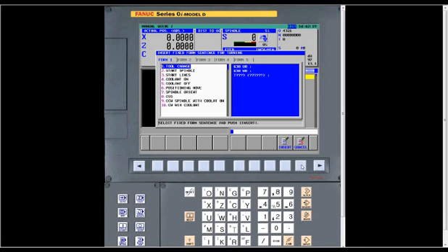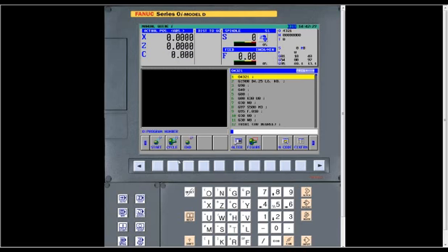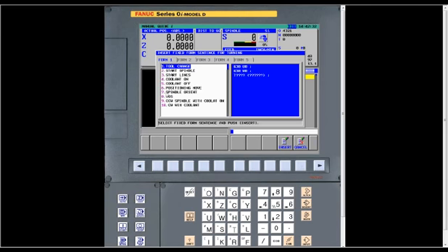different fixed forms. And just to let you know, Form 1 and Form 5 will always be the ones that come up when you go into start or end. Form 1 will be the start ones. Form 5 will be the end. And what you do, you just go in and set them up. As you can see, I've got tool change, start spindle, start lines, tooling on, whatever you want to put there. You just set it up however you want. As I said, Form 1, these are start of the program type commands.